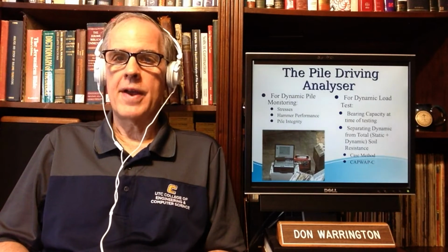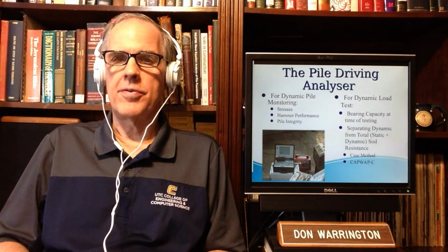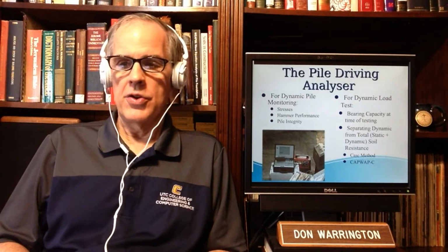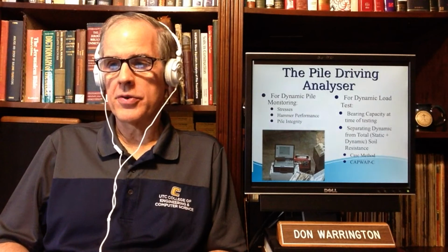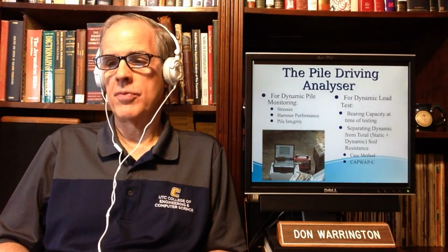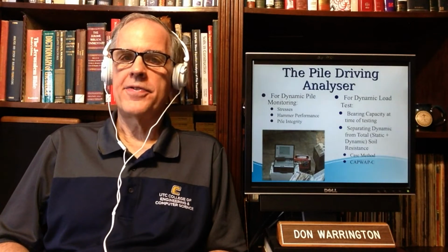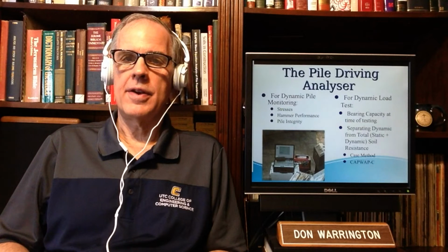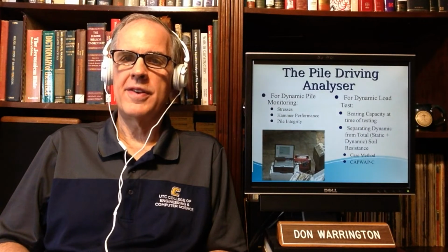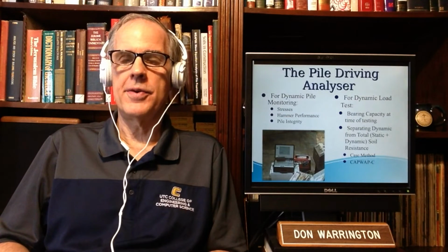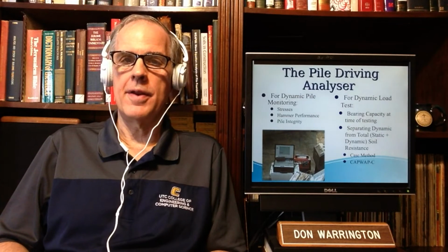Now, I've got something in there which deserves a better explanation. Separating dynamic from total static plus dynamic soil resistance. I think it's fair to say that we don't explicitly do that. With the case method we do, and we're going to talk about the case method in just a minute.